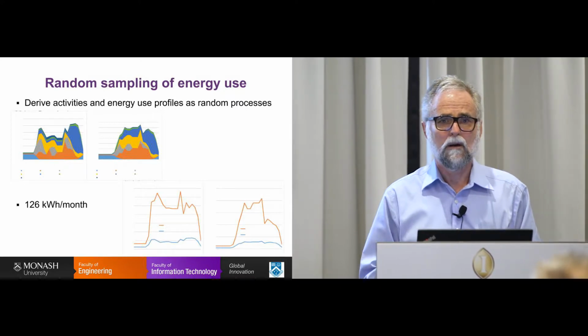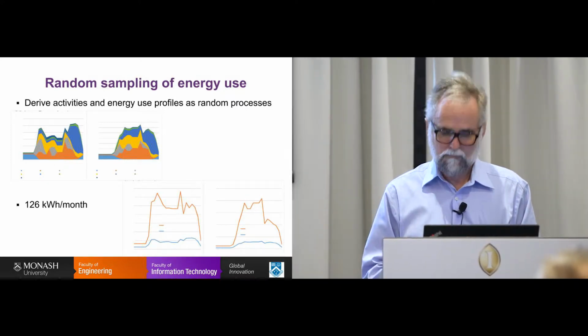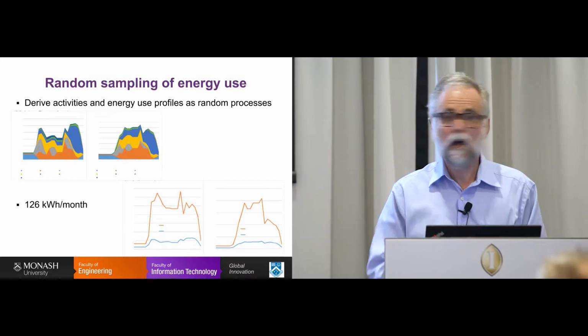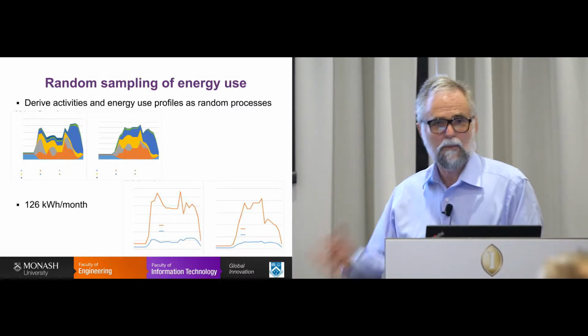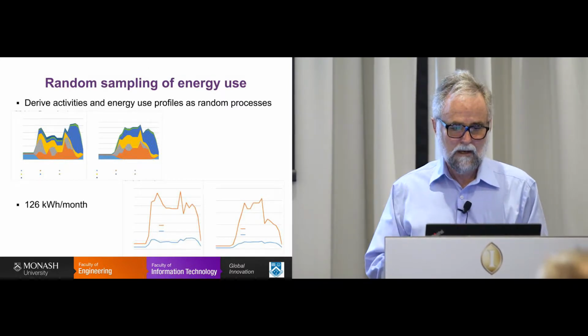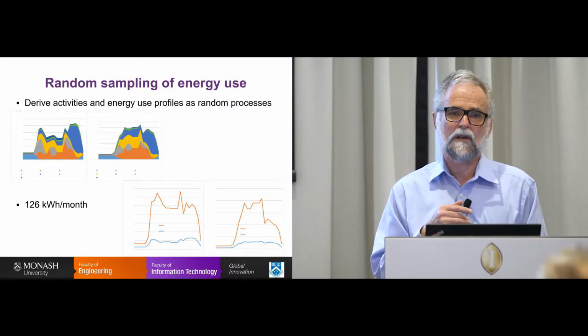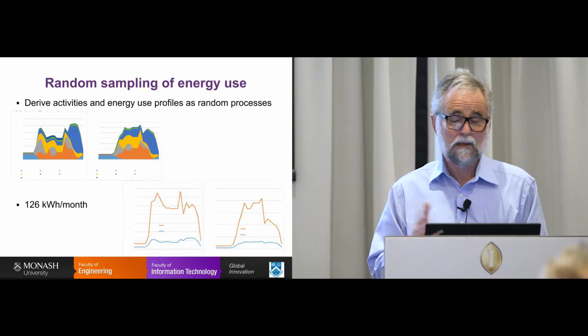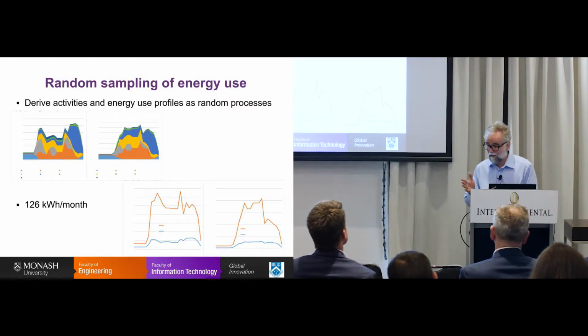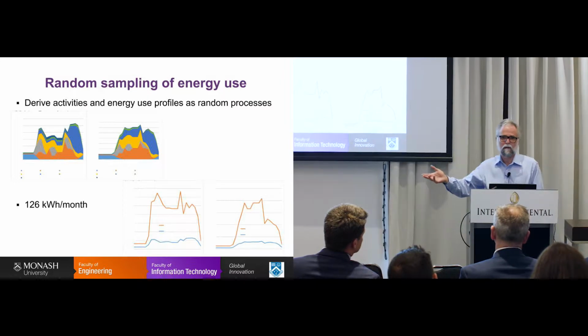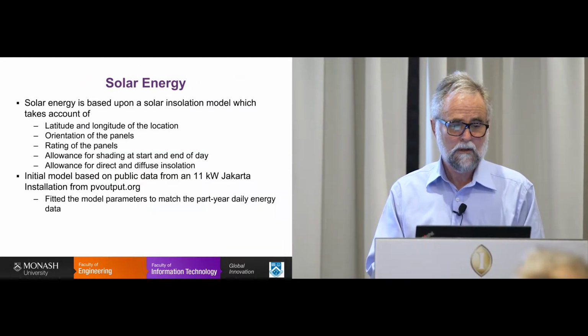So, Ross, are you trying to displace a diesel generator that's already hooked up? No, I'm starting from nothing, just putting in solar panels and batteries. I didn't model diesel, and looking at the results for a small cluster of houses, it's actually cheaper than going for diesel anyway. Even in Indonesia, especially in Indonesia, it's very difficult to deliver diesel oil to remote locations. There's a high transport cost, there are transport risks, and I'm sure there are areas where if people could afford it, this is what you would do. Actually, diesel power would be even more expensive than this.